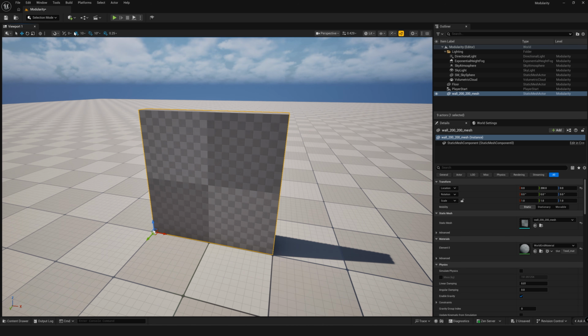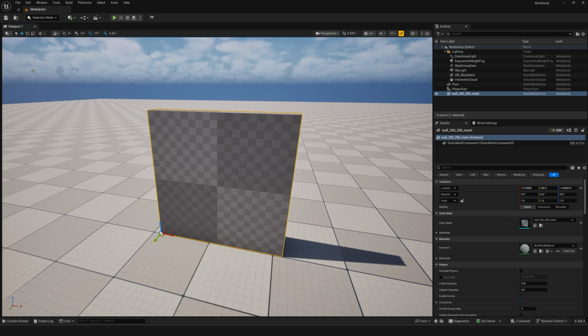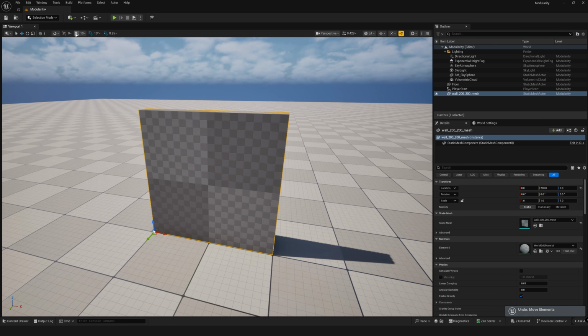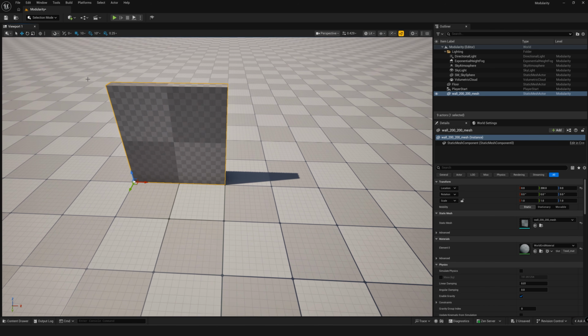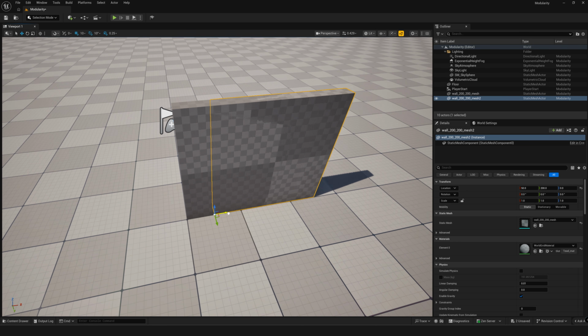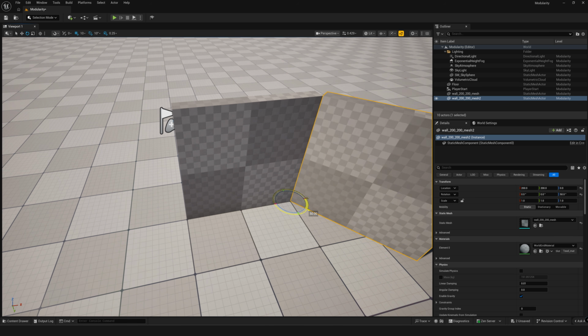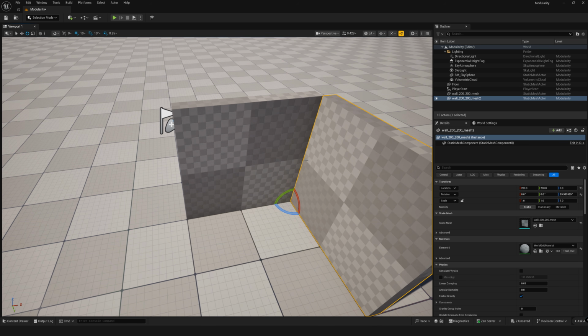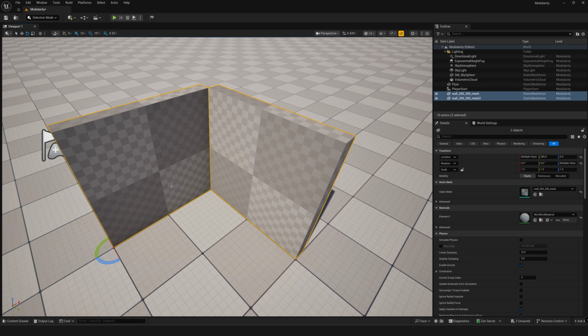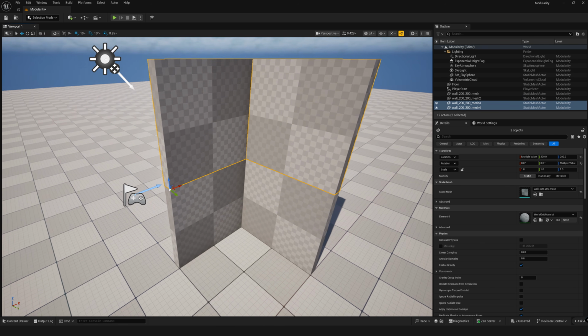That's what you want. If you don't want that, and you just want to manually place it wherever, you just click this and see how it's gray now. It will now turn off without any sort of grid snapping. So let's go back here. And now if you just hold Alt to duplicate your object like this, guess what? It's going to grid snap. And with the rotation, it also grid snaps every 10 degrees. Easy peasy. You can grid snap as much as you want.